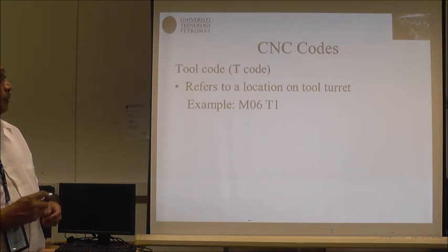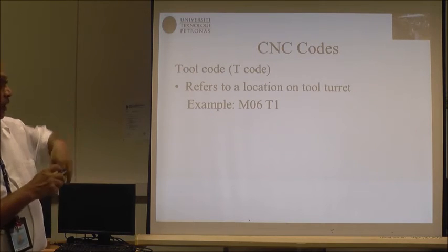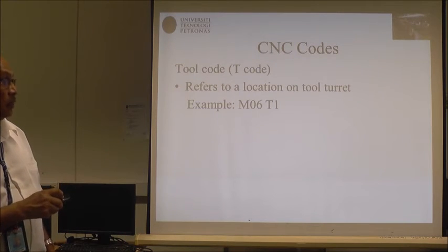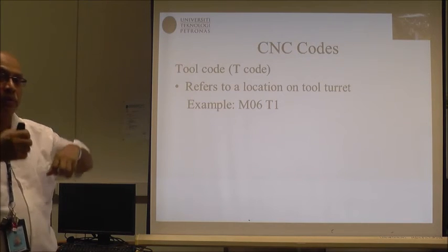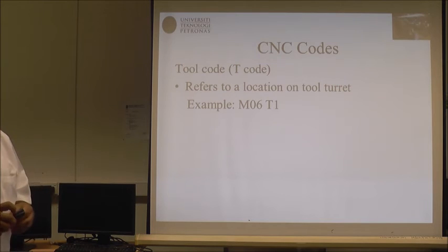And the tool code defines which tool you want in the turret to change. So if you say M06 T1, it will turn and change this tool and take tool number 1 into the turret.